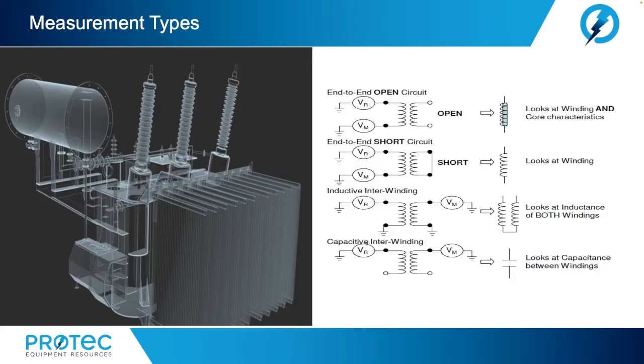To make an SFRA measurement, a transformer must be prepared as it would for power factor and capacitive measurements. Each winding section, high voltage and low voltage, is analyzed separately. Transfer function measurements from high voltage to low voltage may also be made, but these are less effective at detecting movement. Short circuit SFRA measurements, made for example by performing an SFRA on a high voltage winding with the low voltage winding shorted, provide further information about winding integrity and relate to transformer leakage reactance.